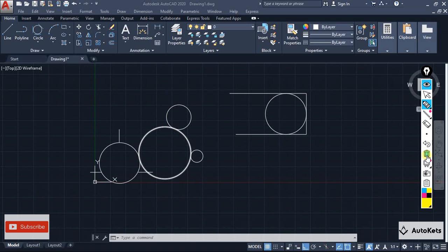There's one condition of the trim as well. If you're working with the trim, then you should know that the trim will only work till the intersection. If you want to trim this line, it will not trim out suddenly like this. There has to be some line or some object, and only if it intersects will it cut. So it is a must that it intersects. This is one criterion for the trim. Let's just see this trim in detail in AutoCAD.